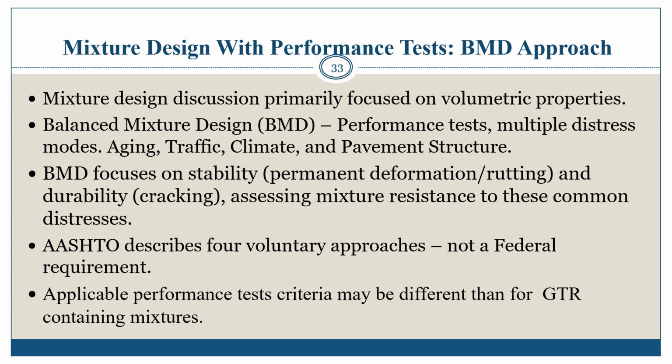BMD is an asphalt mix design using performance tests on appropriately conditioned specimens that address multiple modes of distress, taking into consideration mix aging, traffic, climate, and location within the pavement structure. BMD incorporates two or more mixture performance tests focused on stability, permanent deformation, rutting, and durability or cracking, assessing how well the mixture resists these common distresses.